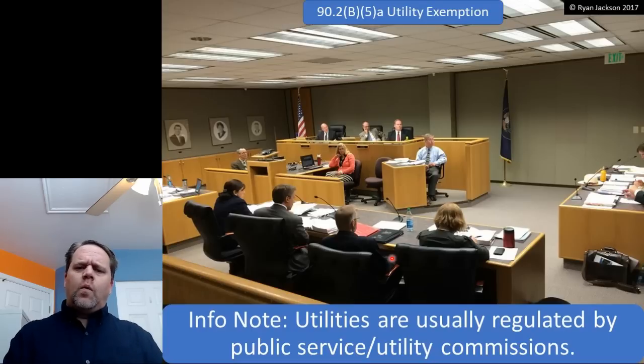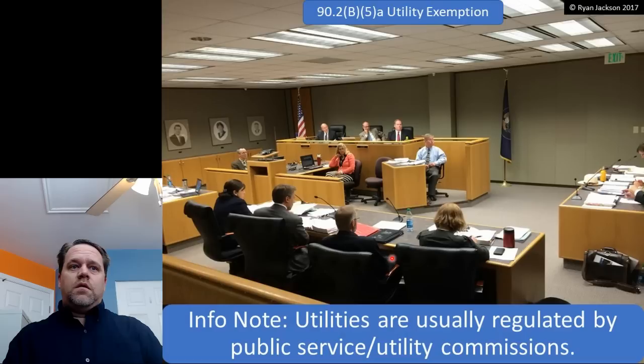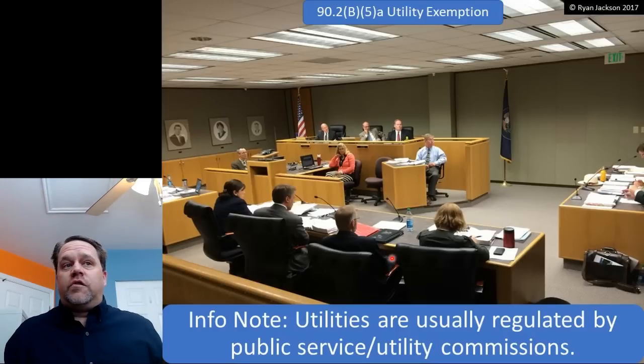And one time we were talking, and he wanted to know about the code applicability, and he said, well, the code doesn't cover us. And I said, oh yeah, it does. You're not a utility. He said, well, yeah, but it's high voltage. I said, it doesn't matter. The code doesn't have a high and a low voltage cap, right? It doesn't start at 30 volts and end at 15,000. There is no starting or stopping point.